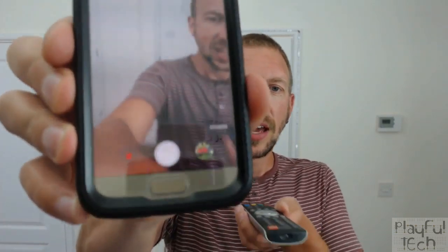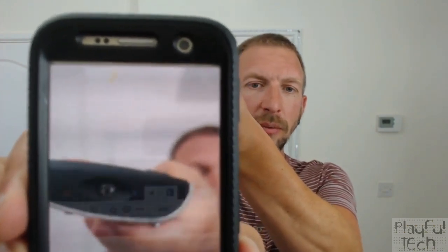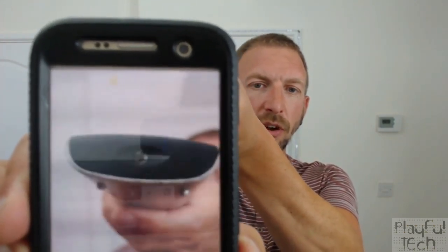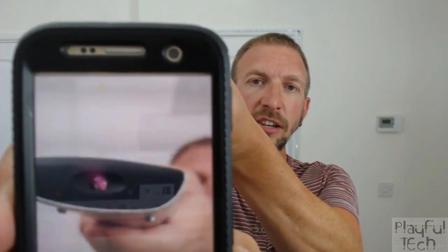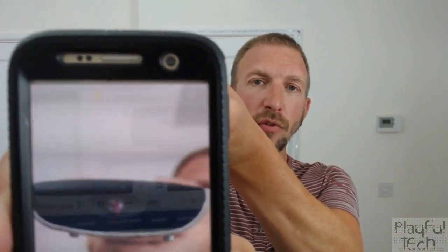Now, even though the human eye can't detect infrared wavelength light, here's a little trick you can play at home. The sensors inside a webcam or a mobile phone camera can detect a broader range of wavelengths than the human eye. So if you load up your mobile phone camera application like this, and then point your television remote control at it, when I press a button on the remote control, you can actually see the LED flickering, and it's visualized as a kind of reddy purple glow normally.